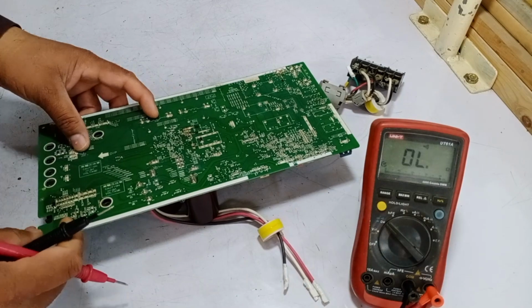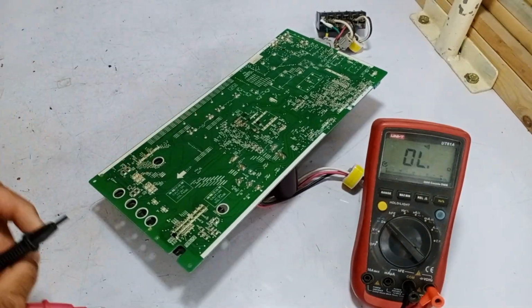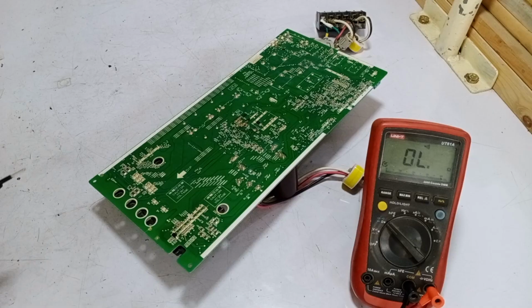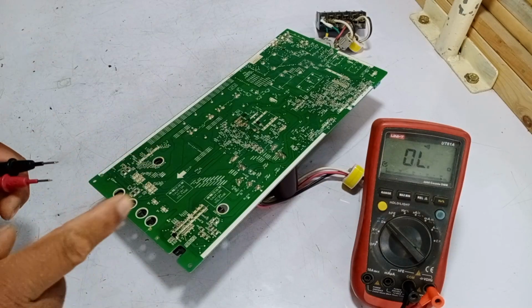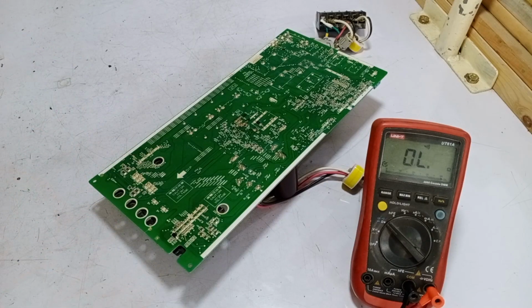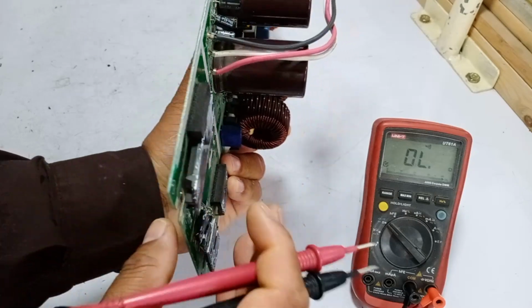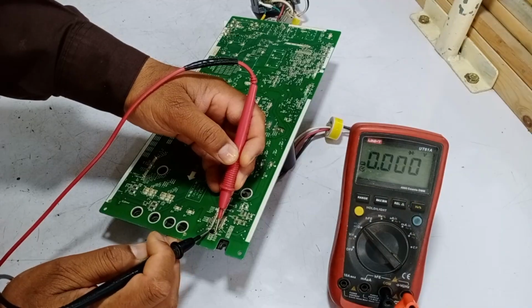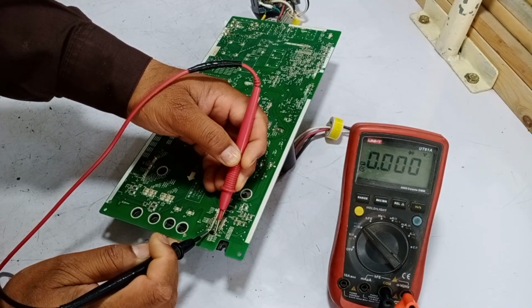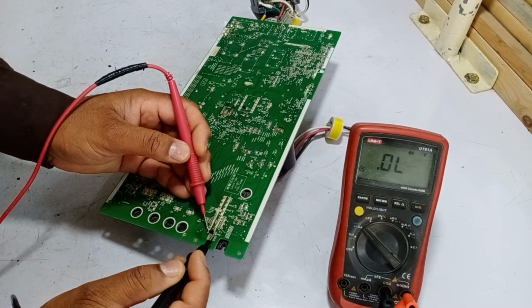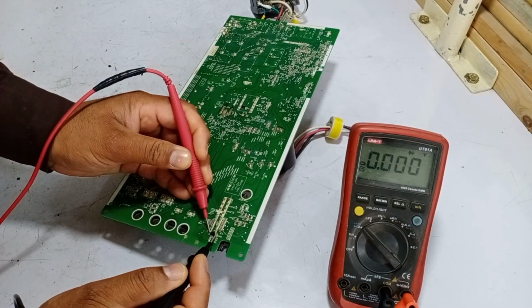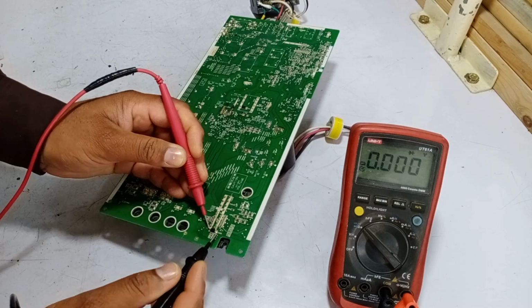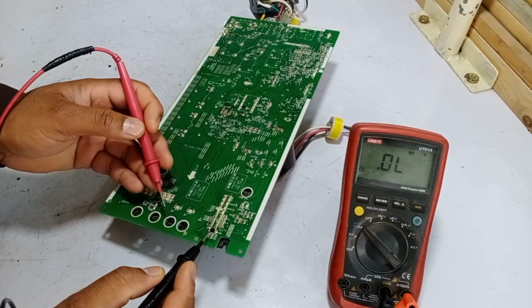After checking all the voltages, it seems likely that either a capacitor is shorted or a diode is shorted, as these components are connected directly to the phase and neutral or positive and negative points in the circuit. Upon further analysis, I found that the IPM has a diode connected to it. When I tested this diode in diode mode, it showed 0 in one direction and 0 in the opposite direction as well. This indicates that the diode is shorted. Upon closer inspection, it turned out to be a 24-volt Zener diode.